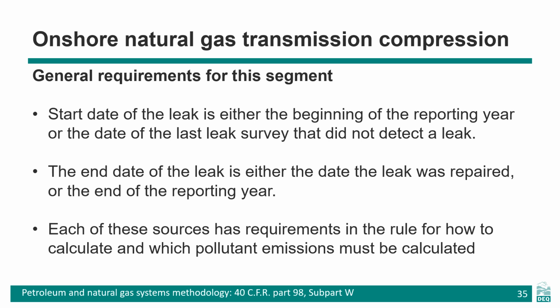Here are some general requirements for this section. For detected leaks, the start date of the leak is either the beginning of the reporting year or the date of the last leak survey that did not detect a leak. The end date of the leak is either the date the leak was repaired or the end of the reporting year. Each source has directions in the regulation on which emissions to calculate for different combinations of how compressors are set up and dependent on whether they have common vent stacks or are routed to flares and other variables.